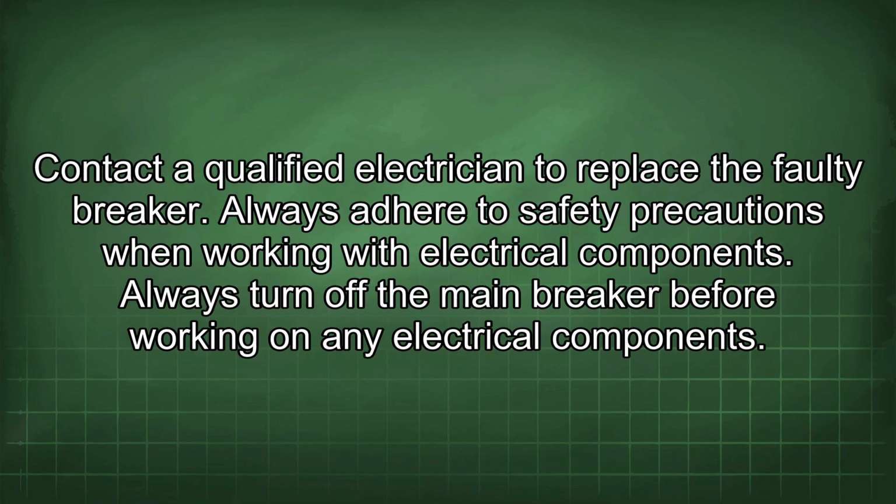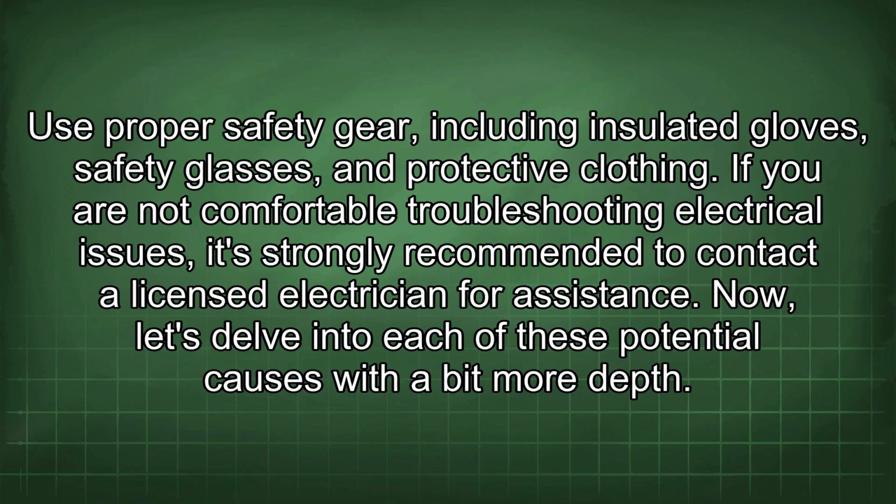Always adhere to safety precautions when working with electrical components. Always turn off the main breaker before working on any electrical components. Use proper safety gear, including insulated gloves, safety glasses, and protective clothing. If you are not comfortable troubleshooting electrical issues, it's strongly recommended to contact a licensed electrician for assistance.